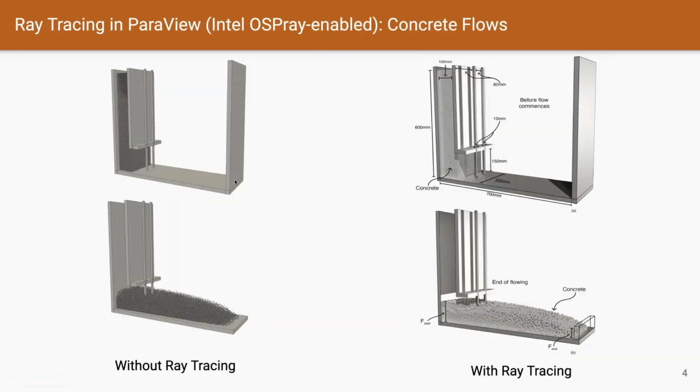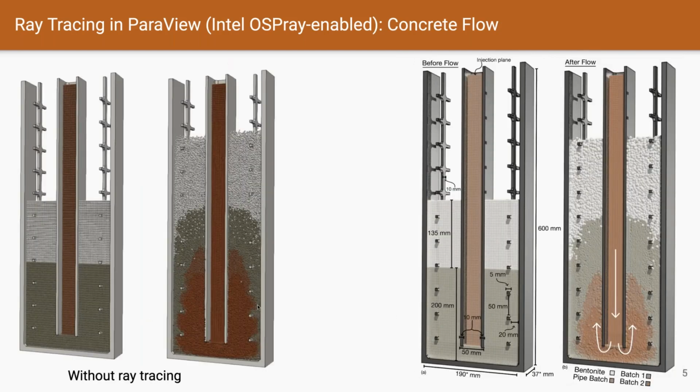We've used it in understanding concrete flows, because this is critical in understanding how a particular concrete gets pumped between those reinforcement bars and whether it clearly covers those reinforcement bars. So you can see how well we can communicate that with ray tracing. And this is achieved all using ParaView with Intel OSPRay plugin enabled. So you can see how different concrete mixes look, whereas if you're just doing typical rendering, we won't be able to